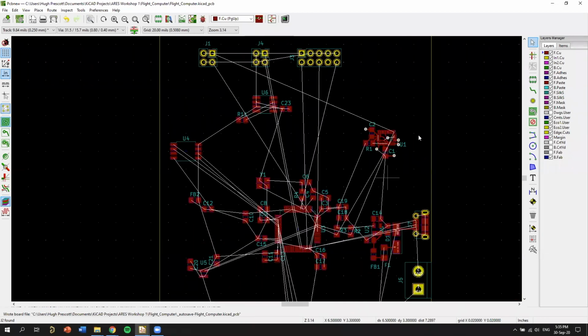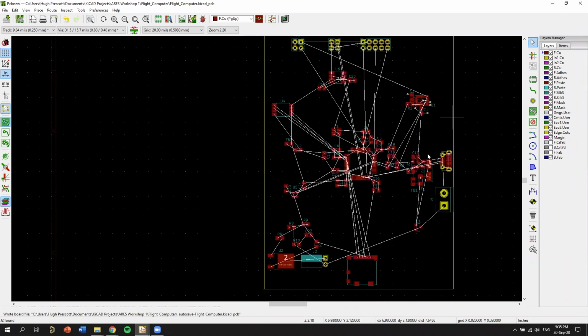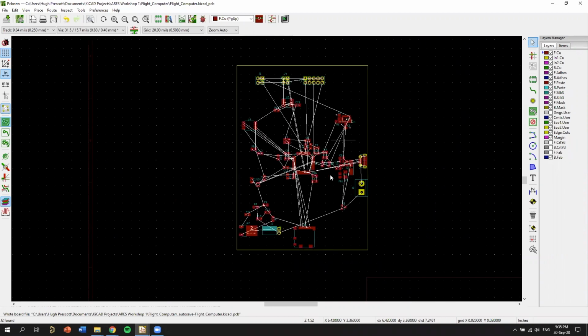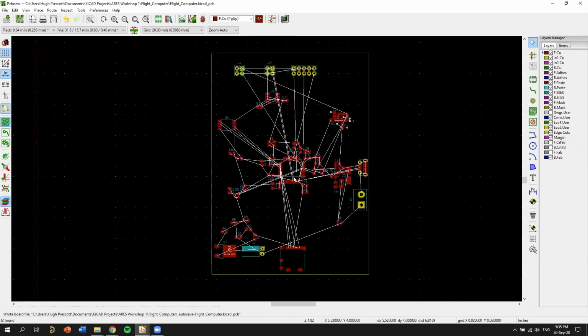If you have a big ground layer, that really helps with signal integrity and preventing things called ground loops. And normally you just put that on the bottom layer of a 2-layer board. But then if you need to route some things on the opposite side of a 2-layer board, you're going to be breaking the ground pour. And normally you want a completely nice uninterrupted ground pour.